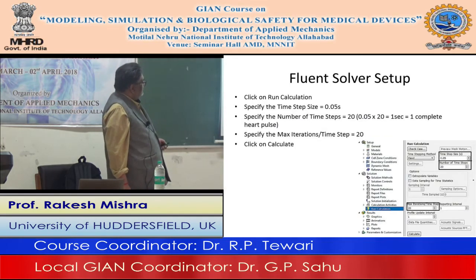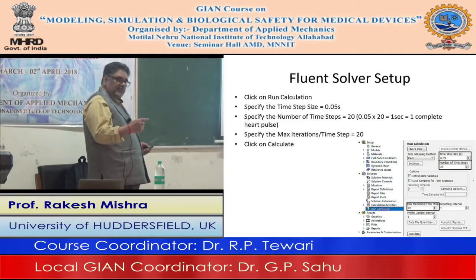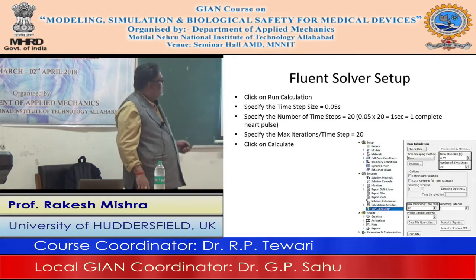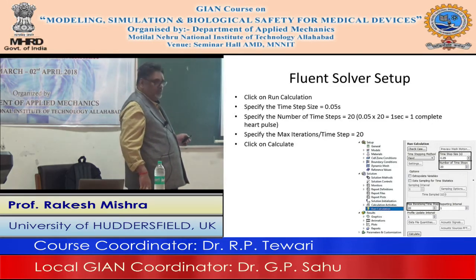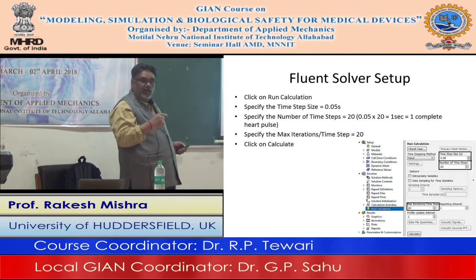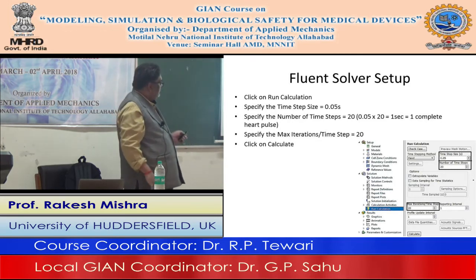But now under transient simulations we have to provide some additional information, that is how close the time steps would be. Like the first time step is 0, second time step will be 0.01, 0.001 or 0.05. That is dictated by the memory you have, or how big the system is. So we typically take, in this case, 0.05. Every 0.05 second, what is the flow that we are simulating? If you're doing a very complicated simulation, take 0.01, take 0.001, depending upon how closely you want to monitor the flow. So in this case, that is what is happening.